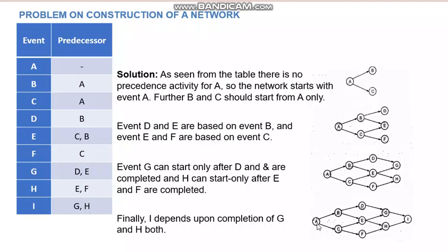Okay. So why are they critical? Suppose the critical path activities are delayed. Instead of 2 hours, you have taken 3 hours, due to whatever reason. So the project duration will now be extended by that 1 hour by which it was delayed. So that's why the critical activity matters. But other activities which are not so critical, if you delay a little also within that loose time that you are having, which is called slack or float, the project will not be delayed.